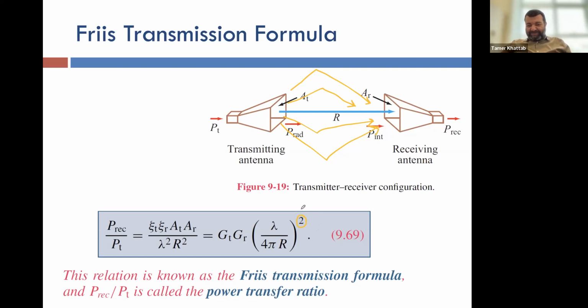How do we figure out that exponent? It's typically done by experimental analysis. We have a transmitter and receiver, we measure the power at different times, and then we take the average of that. Then we do a curve fitting of that average at the receiver side to the expression of the path loss, assuming that we don't know this exponent. So this is going to be n. From that curve fitting, we figure out the value of n. They call it the path loss exponent, right? For different environments, typically this is what changes. The rest stays the same, okay?